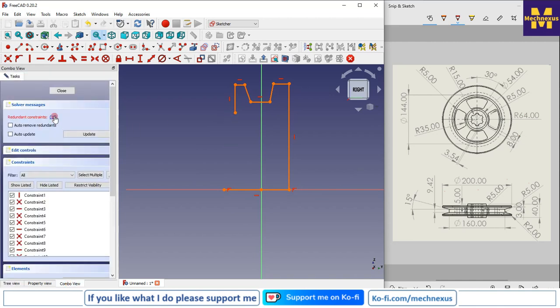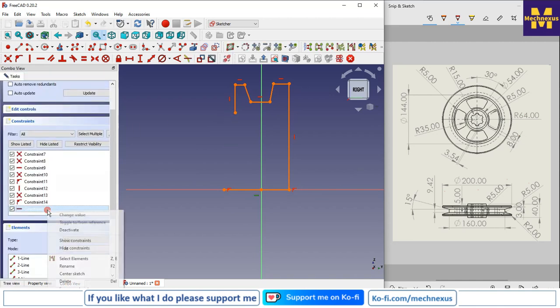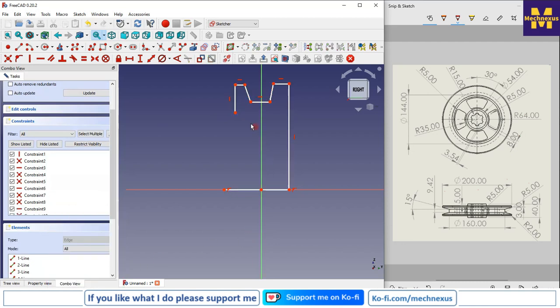Now I will select the conflict constraint and delete it. Now I will select this point and this point and click on merge, and now I will make these two points symmetric. So I will select this point and my middle plane.